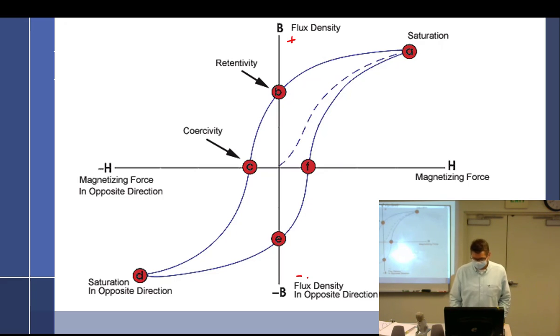But 10 is 10, right? It goes back and forth. So when we magnetize something, let's say I put 5,000 amps through it, there's a point where this part is only going to get so magnetized. It can't just continue to get more of a magnet. If all the domains are lined up, it's done. It's saturated. They're all lined up inside of there, and so you're done. If you were done at 1,000 amps, giving it 2,000 isn't going to make it more of a magnet. 5,000 isn't going to make it more. So that's what saturation is.